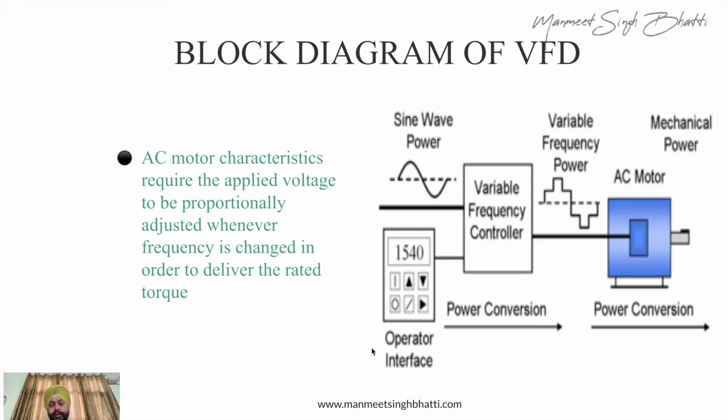And if you see, the power waveform is something like this. This is not a pure sinusoidal. It's more of a pulsed variable frequency power coming. But it is okay with the motor, because based on the change in the flux, the motor automatically gets magnetized and starts working. The effect of this sinusoidal wave and the not-so-perfect sinusoidal wave is not very high on the AC motors. So the behavior of the AC motors remains the same as per the requirement, but you also get additional control on the frequency. So this is the way it is going to work.